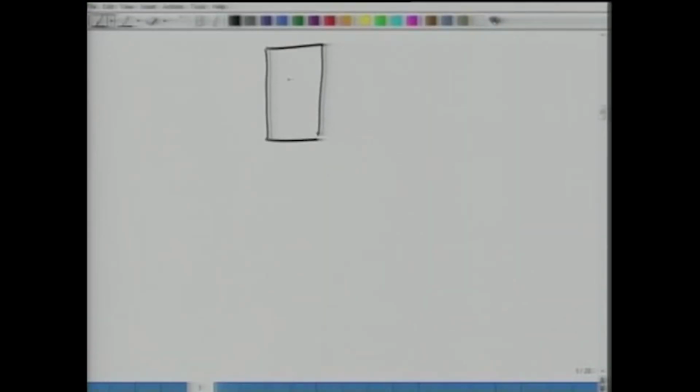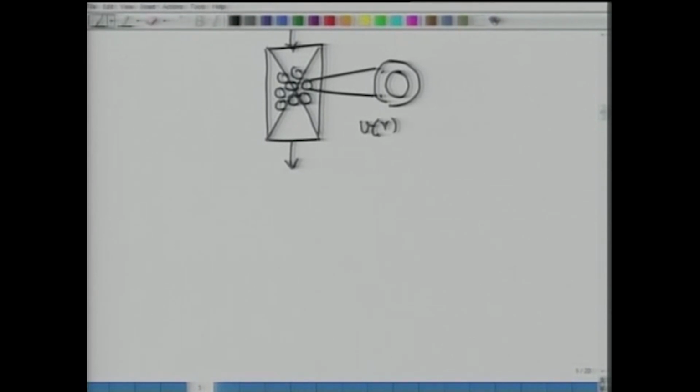So suppose we have a packed bed, a more complex situation, in which different spherical particles are stacked like this, and the fluid goes like this. If you look at one spherical particle, there is a quite complex velocity profile surrounding it. To predict the velocity profile exactly, one requires a software engineering tool like CFD, computational fluid dynamics. Then maybe to some extent we can predict the exact nature of this velocity profile. Otherwise, it's very difficult to predict the fluid flow inside the packed bed.